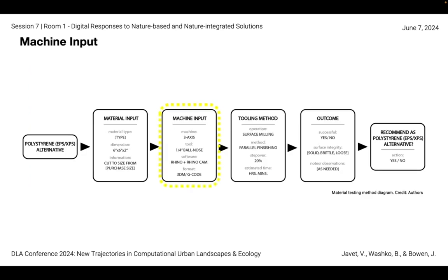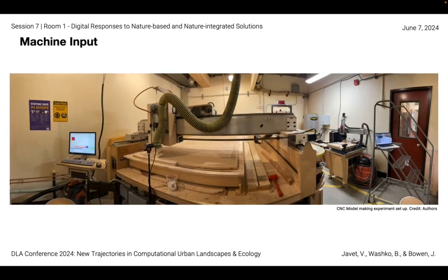With the goal of testing non-standard materials under machining, the primary considerations were how to approach machining speeds and the order of operations. Programming of the CAM operations was done using RhinoCam, a computer-aided manufacturing software plugin for Rhino. When working with polystyrene, its lack of density allows a user to machine the material directly using finishing operations rather than going through an initial roughing pass.